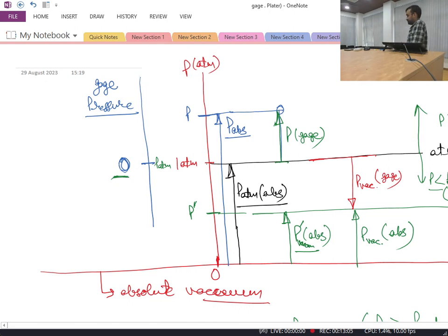normally in engineering practices. Okay, so if you go to your fluid mechanics lab, or if you find any other pressure measurement devices, pressure Bourdon tube pressure gauges you might have seen many times. In these pressure gauges, these are open to normal atmospheric conditions. Their needle is actually pointing towards 0. So they are giving the 0 reading corresponding to the local atmospheric conditions. So these will provide us the value of pressure in gauge.